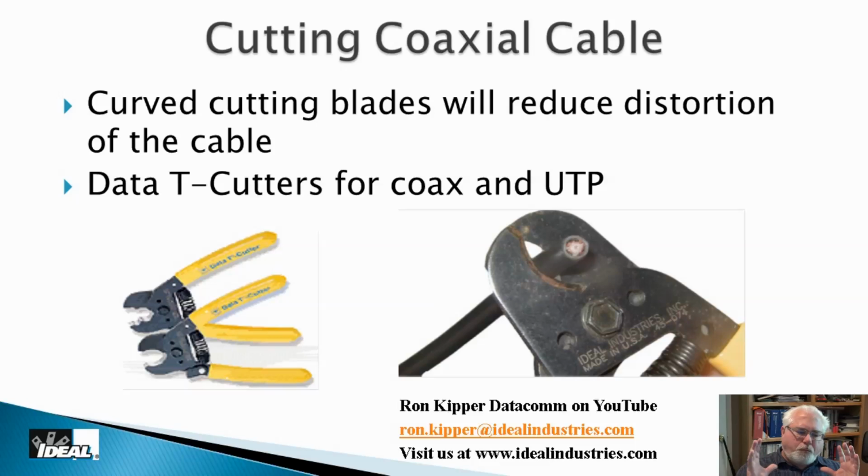Now, when you cut the coax, I don't care what you cut it with, you're going to deform the shape of the cable in some form or another, whether you're using a diagonal or a side cutter or one of these rounded bladed cable cutters. Obviously, it's not good, and the stripping tool we're going to use on the end of the cable hopefully is going to remove anything we've really deformed, but about anything will deform the shape of the cable. But these rounded blade cable cutters don't do a bad job.